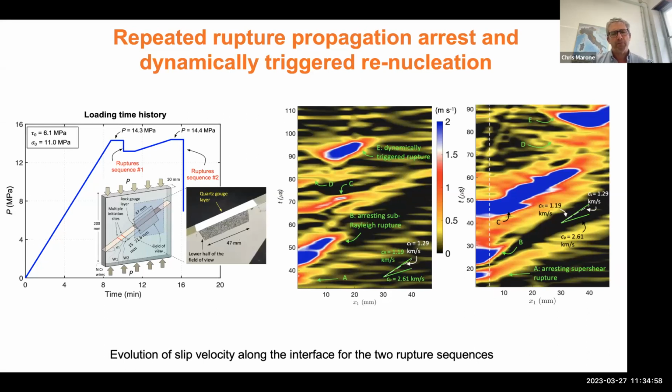Do you have an intuitive insight about why there's such a big difference between, let's call it, the Ruina-Dieterich critical slip distance, and then the Prakash and Clifton one? Because if they're both related to contact junction dimension changes, how do you get this factor of 100?